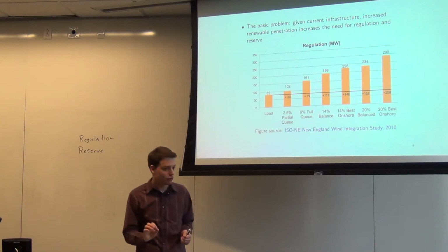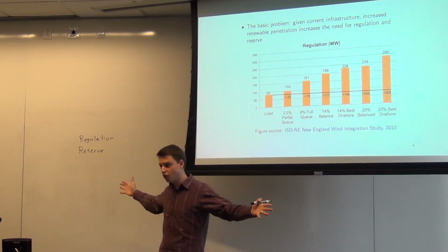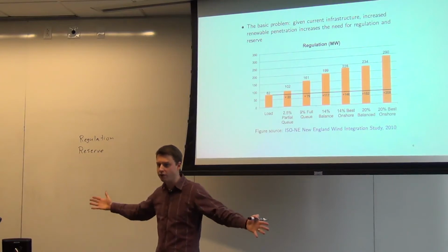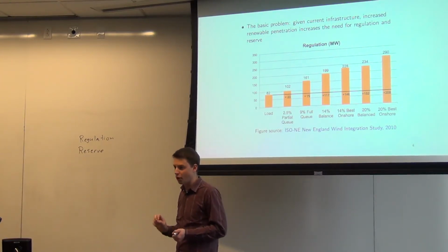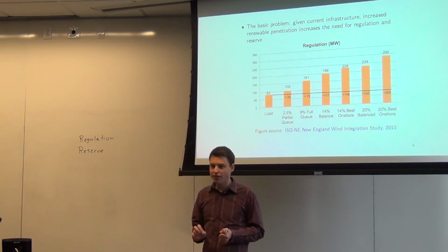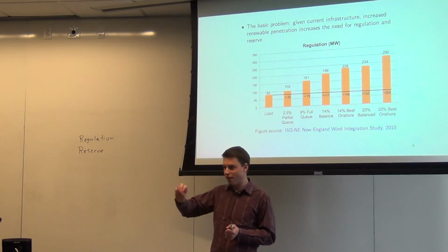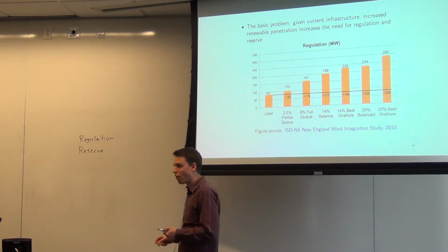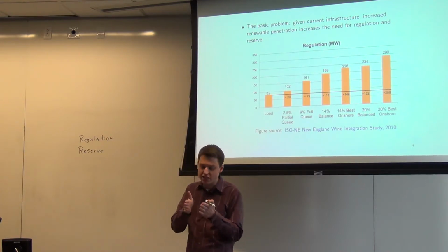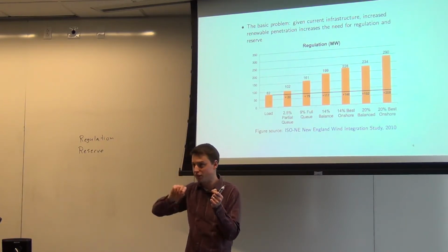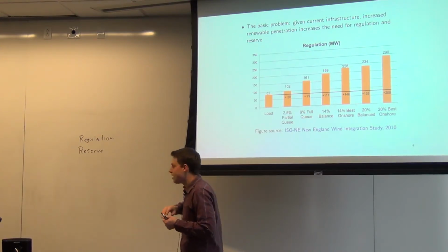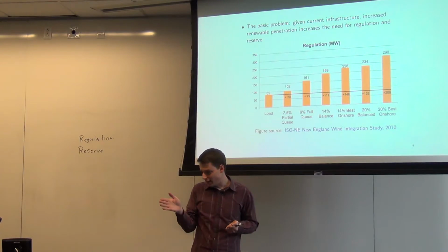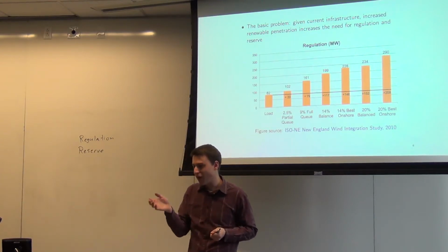And so this, in some sense, is what can be impacted the most by renewables, because one effect of renewables is that if you have a great big solar farm producing megawatts of energy and a cloud comes over, it will instantly drop the amount of power being generated, right? I think some people are working on a solar energy forecasting problem for the class project, and what you see is these smooth lines, and all of a sudden there's a cloud right there, and it just drops off entirely, and you have no energy then. There's nothing like that in typical grid operation, short of a generator actually failing, right?